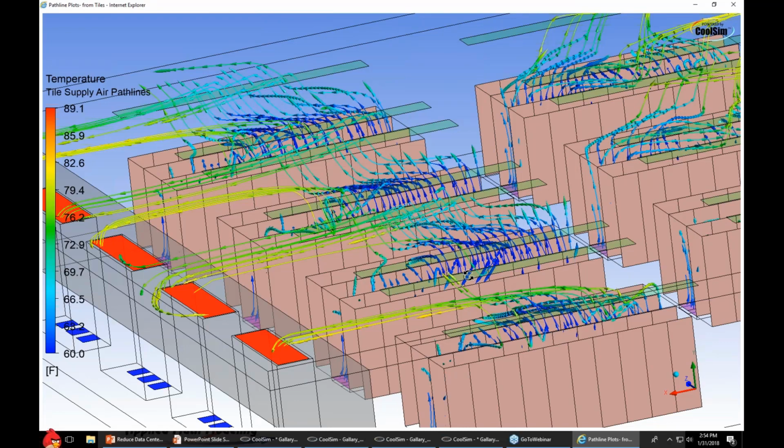What is the maximum rack server outlet temperature that becomes an IT operational problem for rack servers in critical data centers? Gene again. Well, what happens here is the delta T tends to be 25 up to 30 degrees. So if you've got a 70-degree inlet temp, which you'd like to have, then your outlet temp is going to be 110 on some of these servers, and that's getting close to beginning to affect other stuff in the return path. So a 30-degree delta T is not uncommon. It is what people are running today, particularly in these high-density servers.